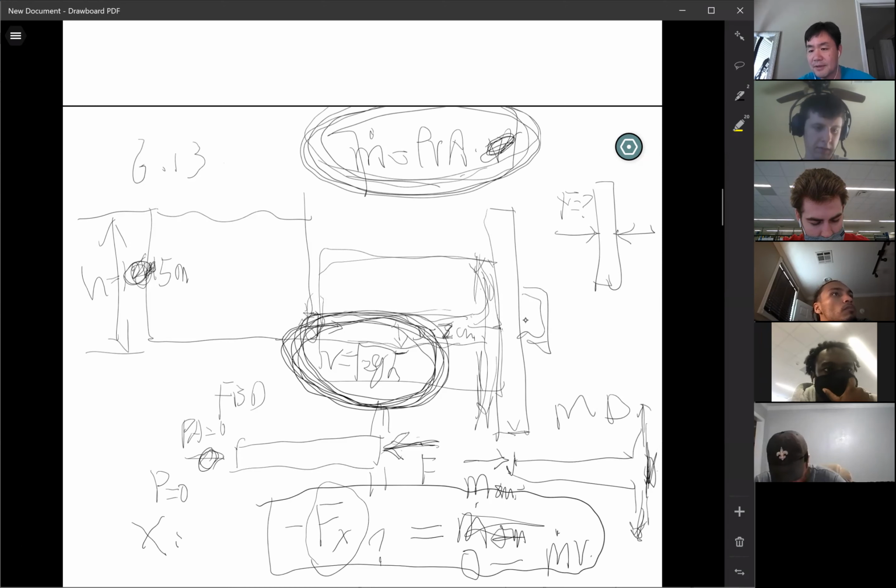Anyway, I still don't see a response. Is that clear enough? You said rho VAV? Is that mass flow rate, rho VA? Yeah, what was the extra V? It's for momentum. Eventually you need the mass flow rate times V. If you get the velocity, can you find the momentum? That's it. Then you can calculate the force required to hold this jet.